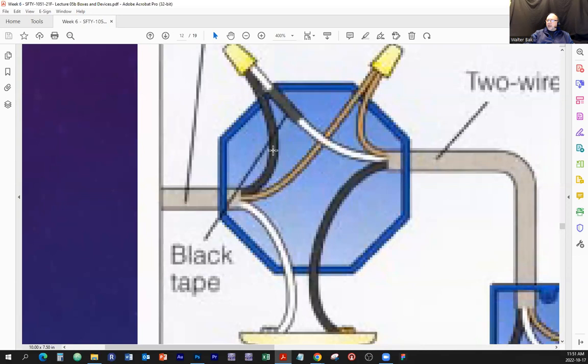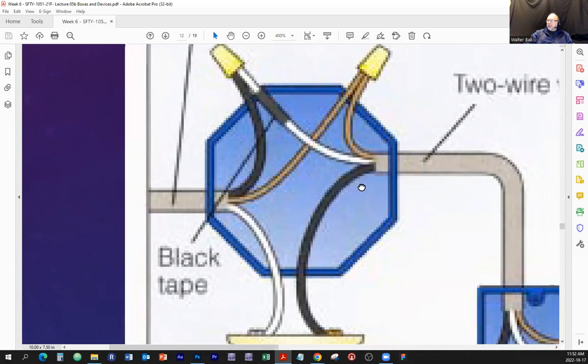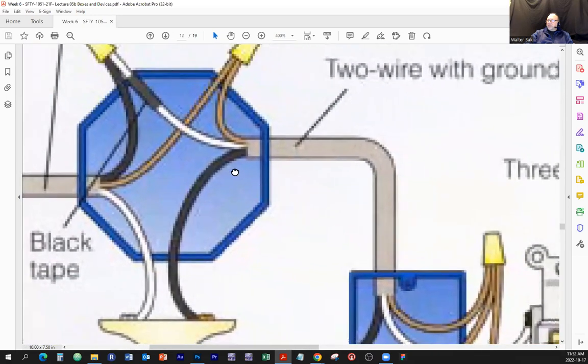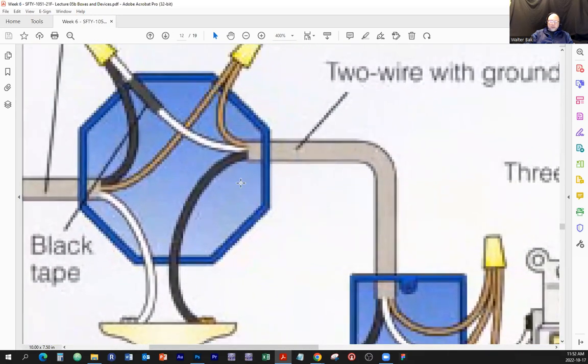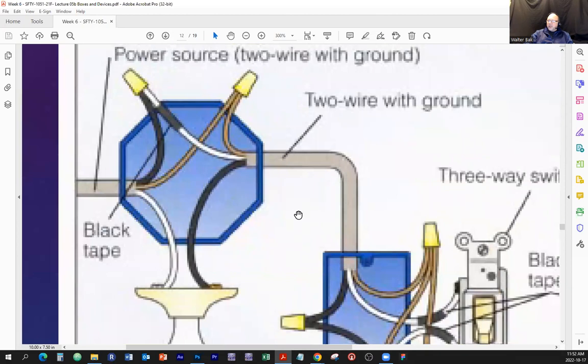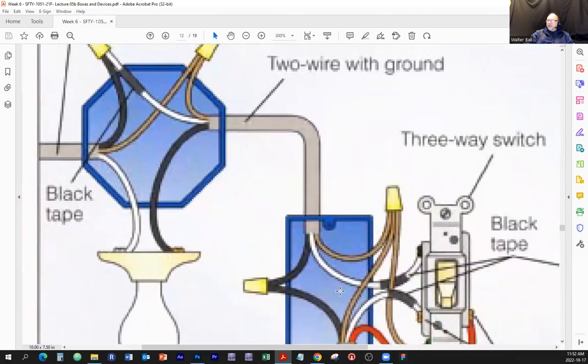And this is the black wire, which is hot. And look, it's connected to a white wire because you only have so many conductors in that cable. So you're going to see in some old situations that there's electrical tape wrapped around that white wire. And it is not that somebody wrapped some tape around and forgot to remove it. No, it is to let you know that this wire is marked.